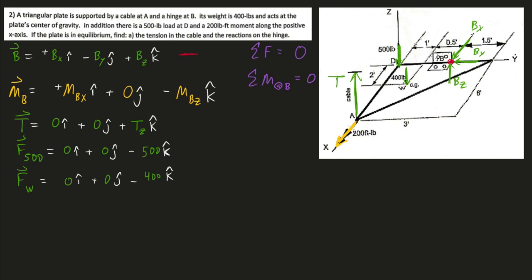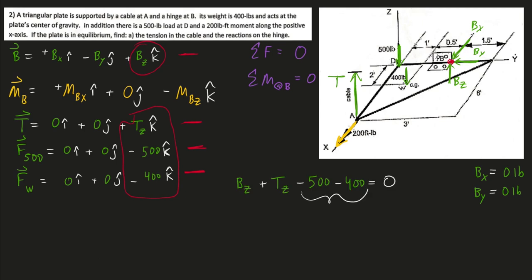So yeah, I'll just add up the x, y, and z components of all my forces equal to 0. So looking at it, if I add all the x components here, the only non-zero one is bx. And the only way for this equation to equal 0 is if bx is equal to 0. And the same thing with all the y components of our forces. So, by must equal 0 as well. So we'll actually have something for our sum of the z force components. So I'll write that out. And we can sum this up to be negative 900. So this will be equation 1.